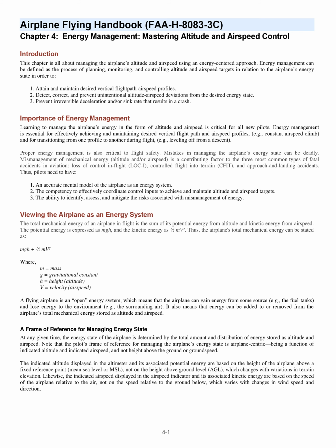Importance of energy management. Learning to manage the airplane's energy in the form of altitude and airspeed is critical for all new pilots. Energy management is essential for effectively achieving and maintaining desired vertical flight path and airspeed profiles, for example, constant airspeed climb, and for transitioning from one profile to another during flight, for example, leveling off from a descent. Proper energy management is also critical to flight safety. Mistakes in managing the airplane's energy state can be deadly.